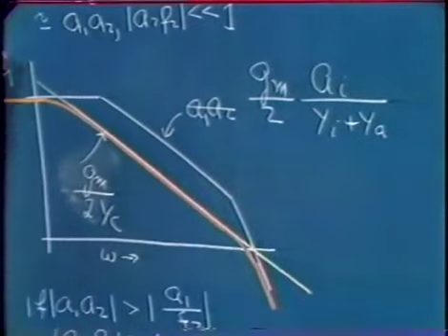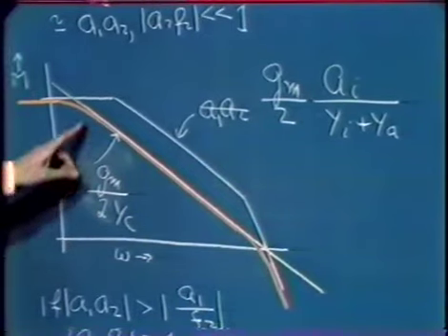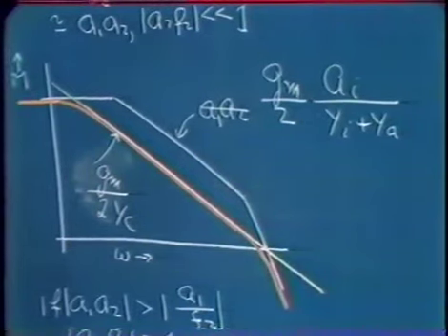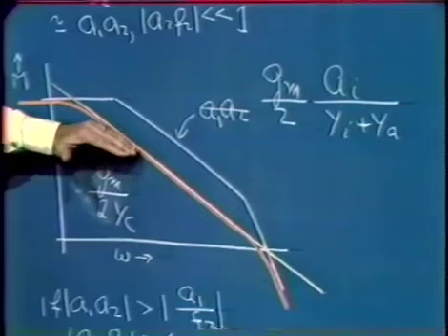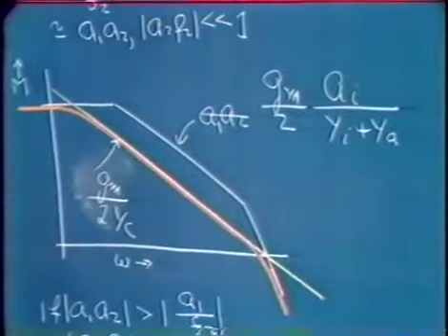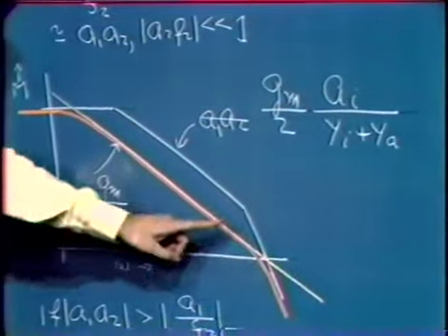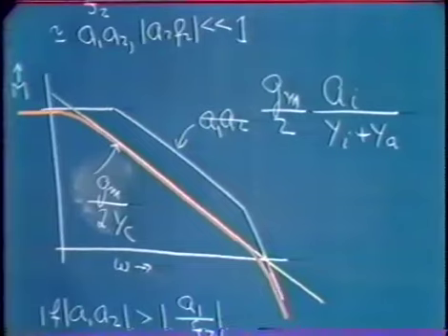So we plot those two quantities once again, as in our general discussion of minor loop feedback. We'd estimate the overall forward path transfer function of our system, in this case the open loop transfer function of the operational amplifier, as simply the lower of those two curves at all frequencies.